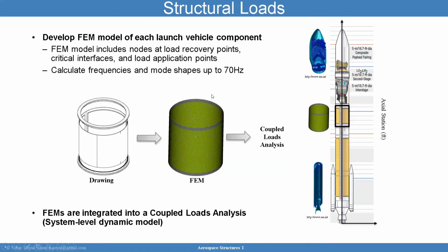So, if you recall, you can develop a finite element model of each launch vehicle component, and the launch vehicle component will then be assembled with other launch vehicle components to form a full vehicle model. This vehicle model usually will be coarse enough for dynamic analysis. This analysis will be sufficient to extract frequencies below 70 hertz, mode shapes and frequencies.